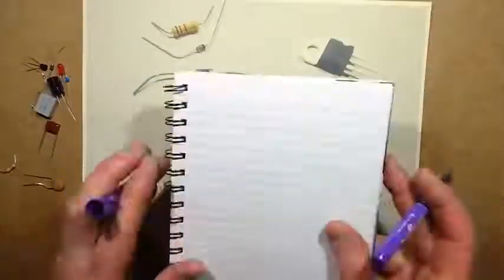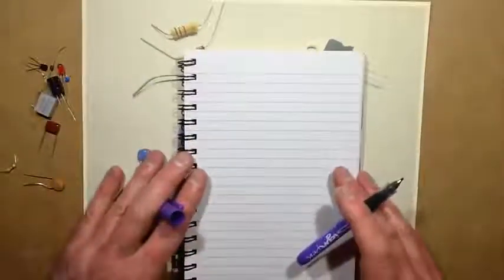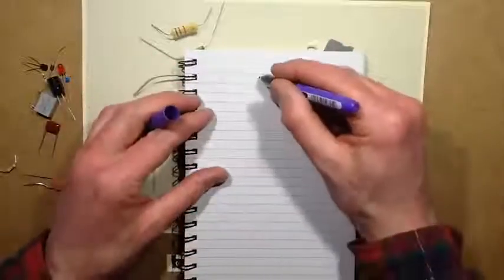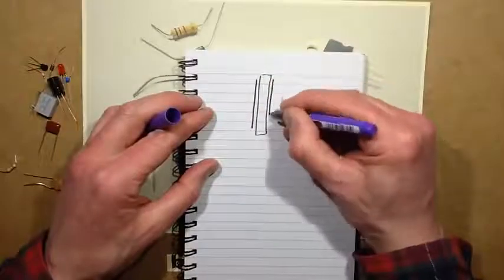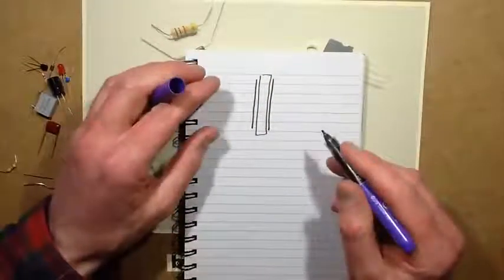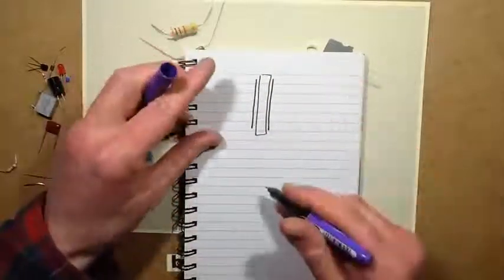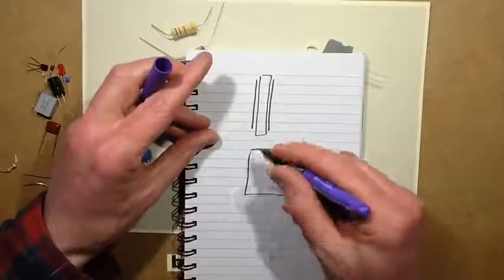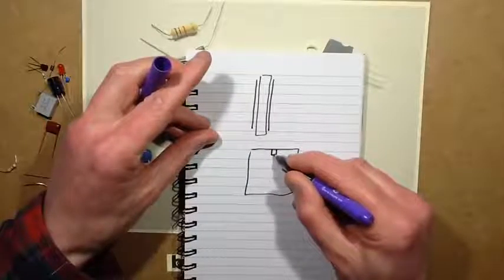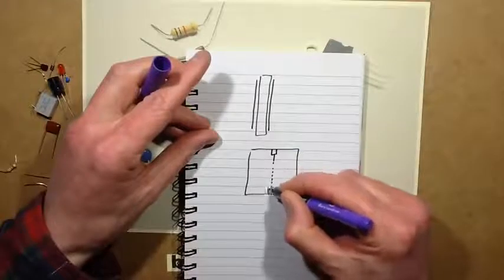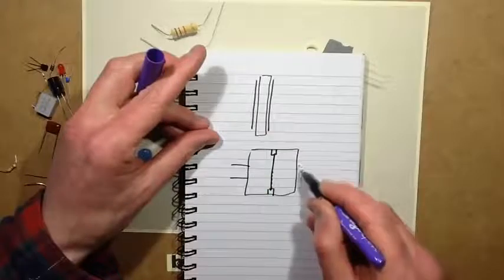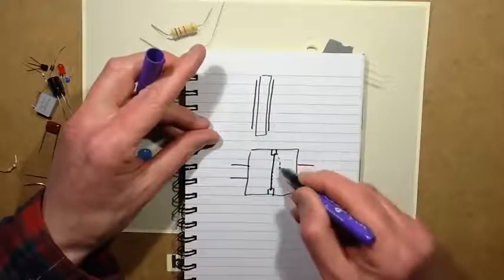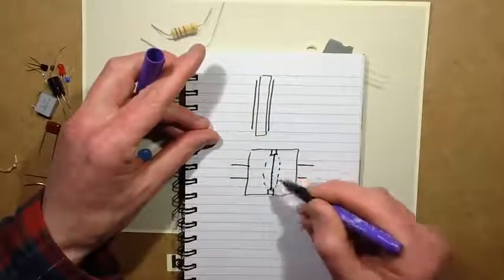So let's move on to capacitors now, because they're quite interesting. So a capacitor, in its most basic form, is a layer of insulating material with a conductive surface on each side. And the best way to describe a capacitor in the water flow theory is a chamber with a diaphragm in it that stops the water flowing directly through. And that diaphragm can flex a certain amount in either direction.